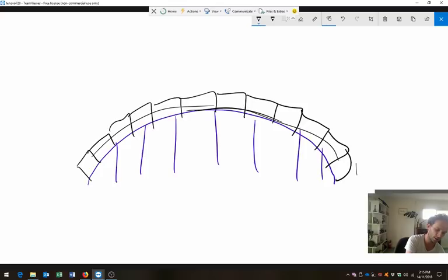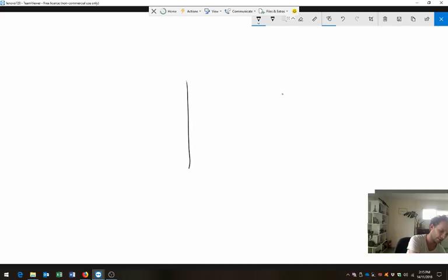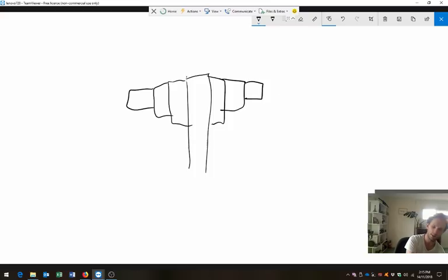But usually, if we're going with a variable depth bridge, we'd use a balanced cantilever. So start at a central pier and begin working your way on either side. You can either do this with precast segments or cast in situ. If you use cast in situ, you will get a longer span bridge than a precast, because the precast elements simply get too large if we're getting too big spans.